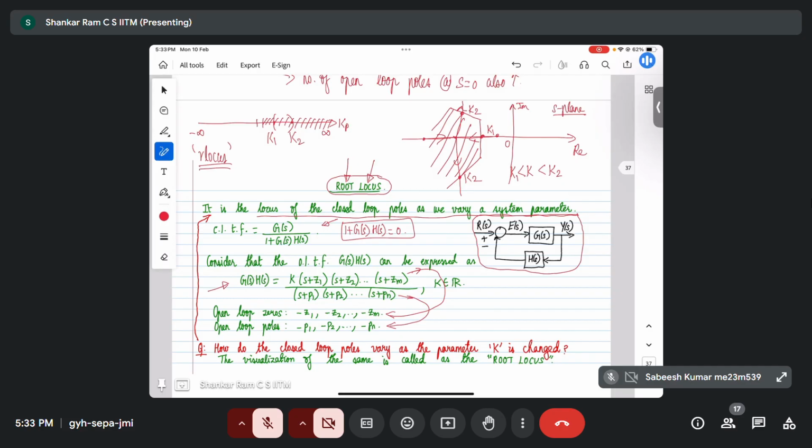Even in the case of, let's say, brake control and steering control and so on, you will use root locus to figure out the range of control parameters which will satisfy both closed loop stability and closed loop performance. You will get a finite range, which you can then take to the actual vehicle and test. We will be doing it as part of the projects.